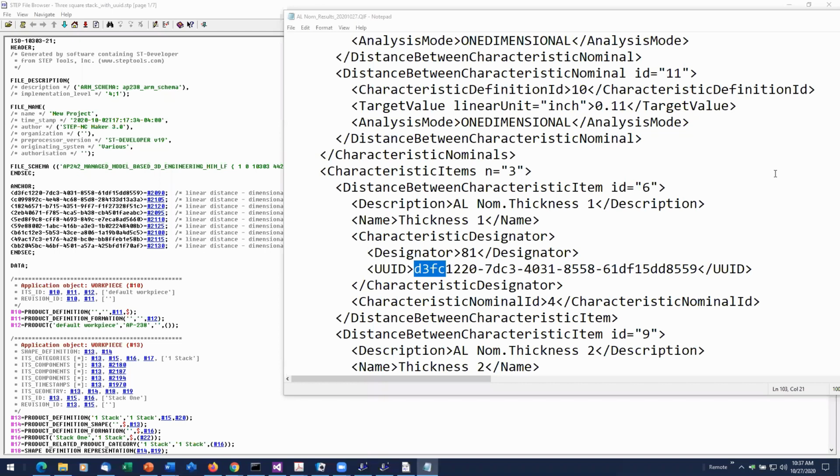We've kind of done some of that because the twins are the models that you want to keep. So in use case one, the condition of assembly twin is the one that's going to be put back into the PLM system. Whereas the MTConnect data that's streamed from all 4 robots might be kept on the shop floor for a little while, but wouldn't, I think, need to be archived.